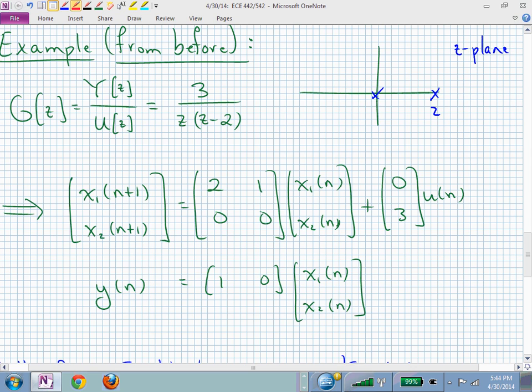And if we don't have any zeros, we have two infinite zeros, and where are they located? At infinity. Right? Where are their angles? You could have gotten some points if I said, where are the infinite zeros? And you say, oh, at infinity. Well, I have to give you some credit for that. They are at infinity, but now where's the fundamental angle? 90 degrees, because it's 180 divided by 2.